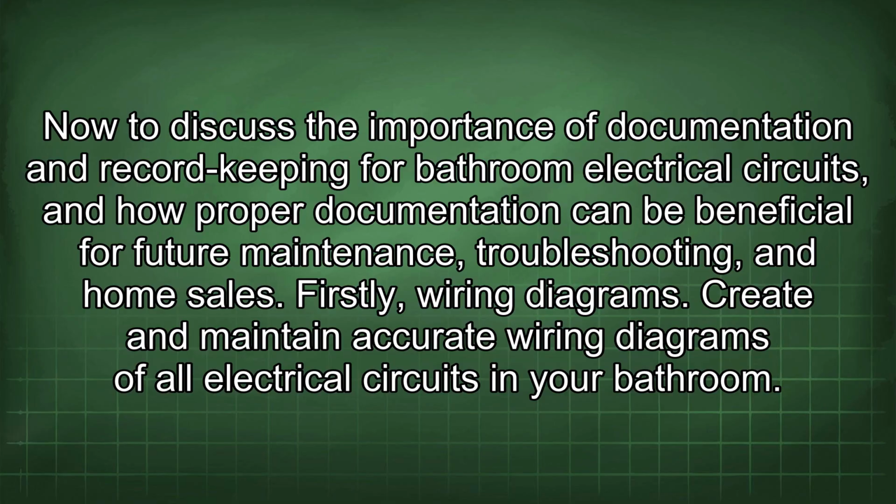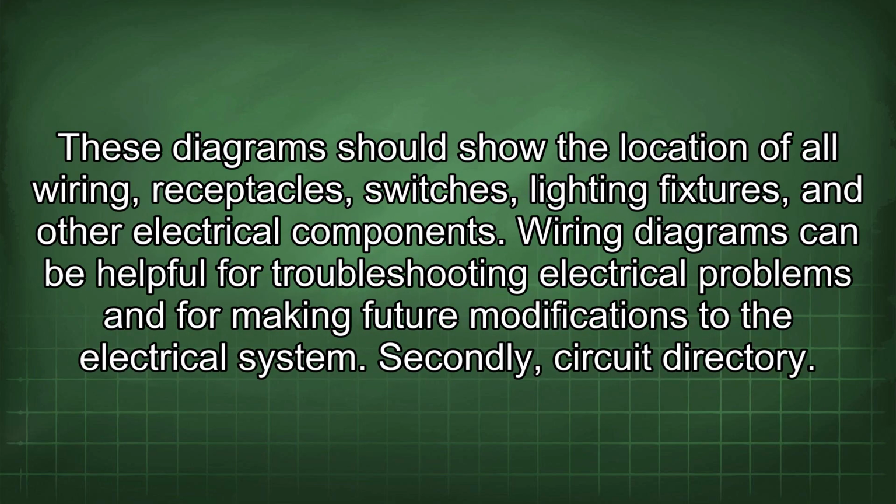Firstly, wiring diagrams. Create and maintain accurate wiring diagrams of all electrical circuits in your bathroom. These diagrams should show the location of all wiring, receptacles, switches, lighting fixtures, and other electrical components. Wiring diagrams can be helpful for troubleshooting electrical problems and for making future modifications to the electrical system.